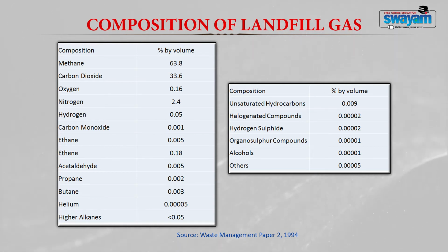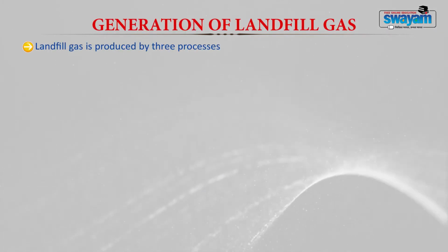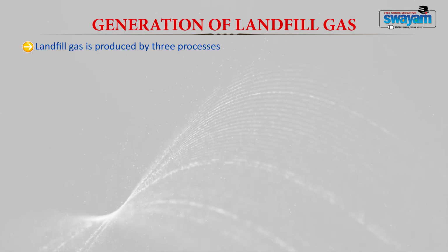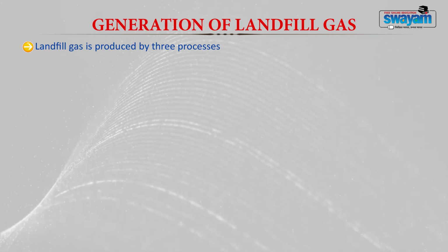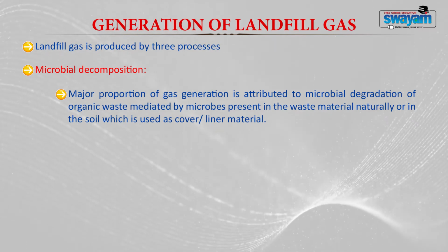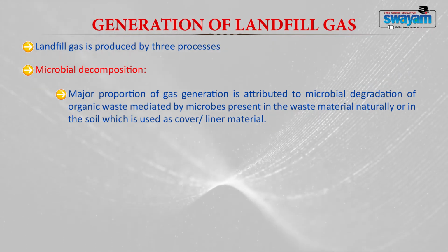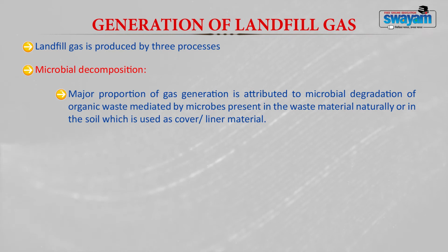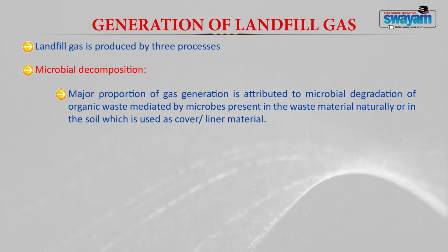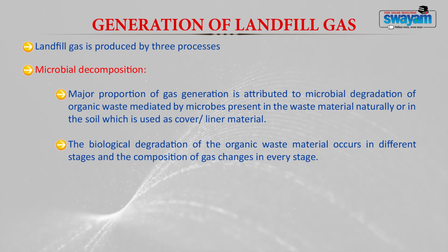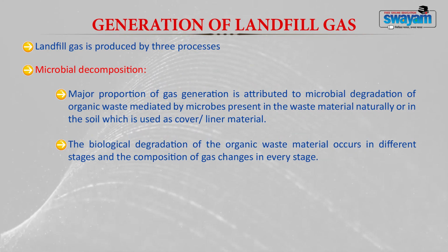of your landfill gas. Now, the landfill gas is generated by three different processes within the landfill. First is microbial decomposition, second is volatilization, and third is chemical reaction. In microbial decomposition, a major amount of gas is produced. Here the organic waste is subjected to microorganisms, they degrade the waste and generate a major proportion of gas. The microorganisms can be present either in the waste material or in the soil which you add or use as a cover or liner material. The biological degradation of the organic waste occurs in different stages and depending upon that, the composition of gases also